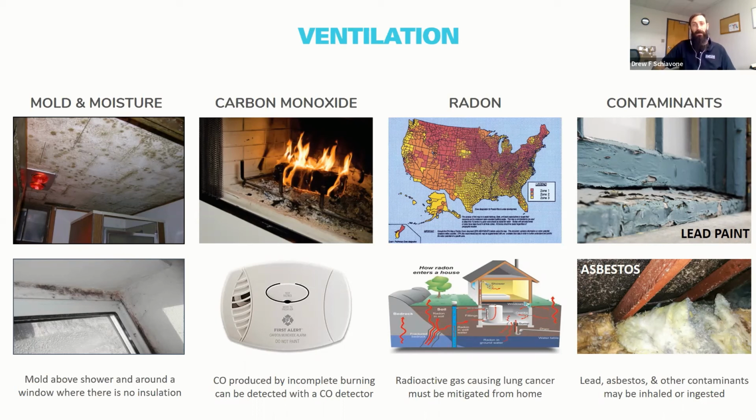Carbon monoxide, as I mentioned with any combustible device, lower efficiency, improper combustion can lead to carbon monoxide. It's odorless and it's invisible. It can also result in sickness and can be lethal in high enough concentrations. So there are things to be on the lookout for if you have inefficient, more yellow flames instead of blue, or if you have rust or corrosion on your fuel burning system, you may want to look into the carbon monoxide.